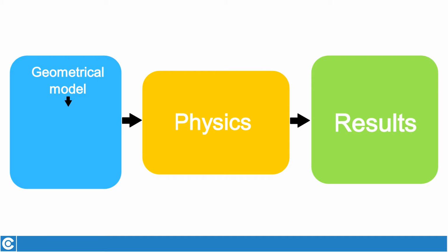First, you prepare the geometrical model, meaning that you either create CAD of your system in CENOS or import elsewhere created CAD in STEP or IGS format. In the second step, partition and group, you need to unite your model in one single simulation domain, and from that extract and name volumes and surfaces of your system, such as workpiece, inductor and terminals.